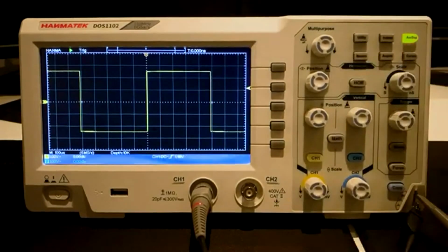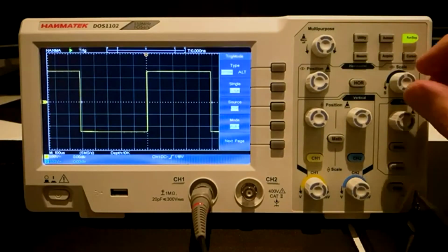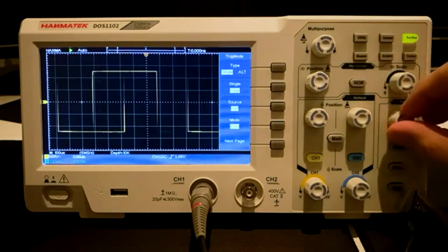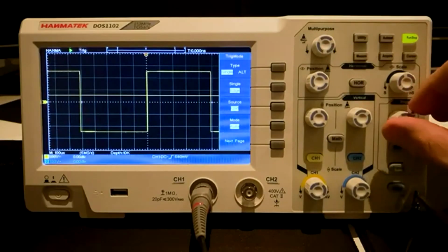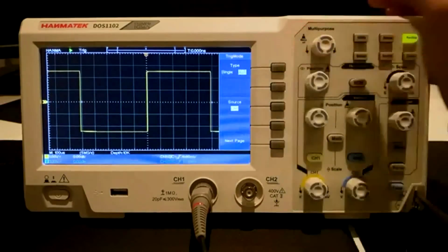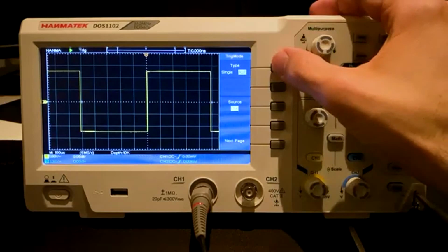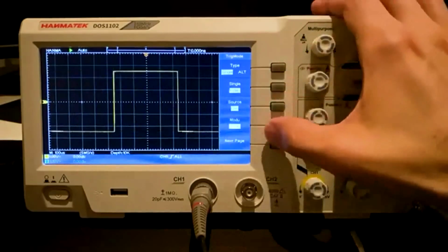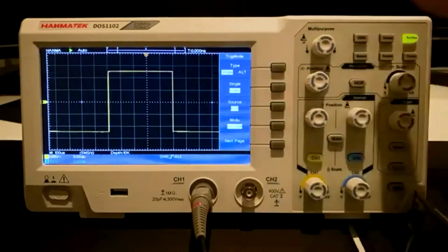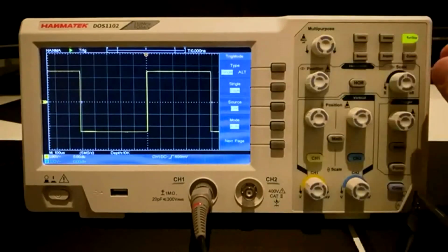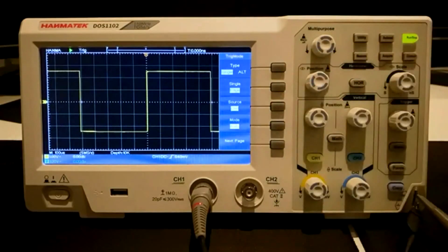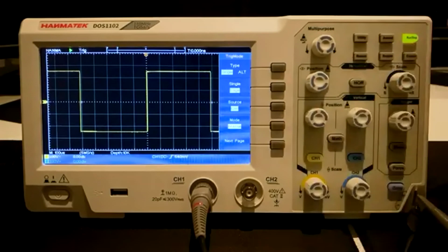The trigger menu button selects the trigger system. The trigger level rotary knob sets the trigger voltage. Single monitors one channel for triggering and alternate monitors both channels. A distinction is made between edge and video for the trigger signal. When video is selected, you can choose between the different video formats NTSC, PAL and SECAM. The trigger signal distinguishes between auto, normal and single.